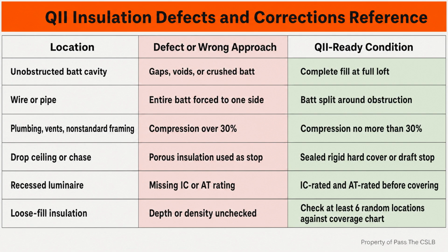California also requires insulating materials to carry the applicable state certification. That makes procurement part of quality control. A product that appears thermally similar is not automatically acceptable when the project requires certified material and documented performance. The clean sequence is easier to manage than the repair sequence. Framing must leave access for the required barrier details.